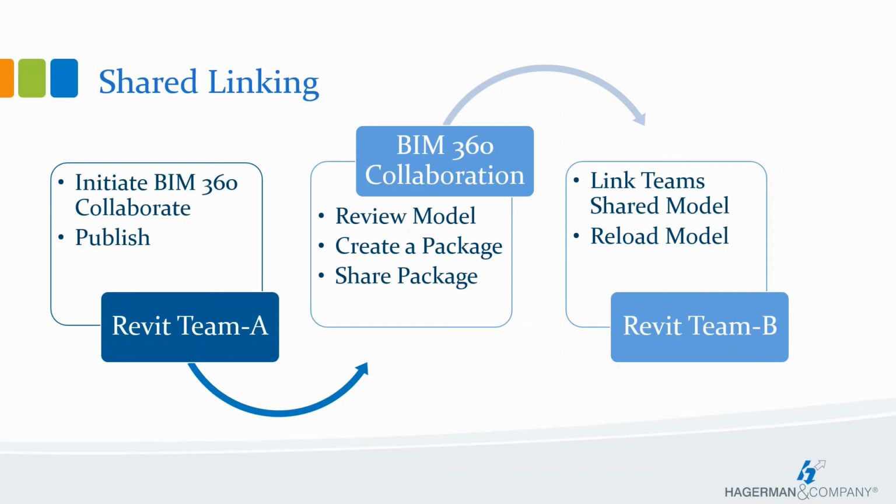To package and share the team, open up Design Collaboration, select the swim lane timeline to activate it. You're going to select Create a Package, review the changes to the model, select and save the views that are to be shared, and select Share. Once Share has been selected, it'll put that into that shared folder. In Revit, they can open up the host model again and initiate links or update those links. And they can periodically reload those. And then again, if you want, you can enable the copy monitoring as well.